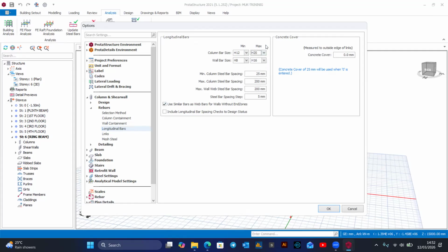But even still, when you find that your client is well funded, you can design up to 32. But what is going to limit you here? The client can have the money to buy that T32. But if you check on the manufacturer, where are you going to get that steel? Do they have that high bar size? If they don't have it, then you can put it to the one which is next to 32.